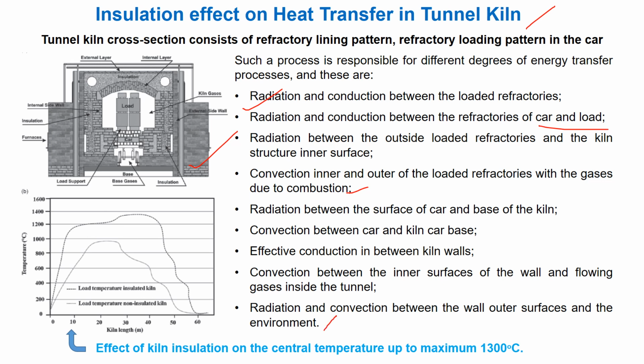Control over fuel consumption and maintaining the desired kiln temperature are always challenging tasks. Thus, insulation is mandatory to achieve the desired temperature with minimum fuel consumption. A typical competitive study shows that the same kiln may have a maximum temperature of only 900 degrees centigrade, whereas insulation may boost it up to 1300 degrees centigrade. However, insulation quality and thickness critically influence achieving the desired temperature profile.